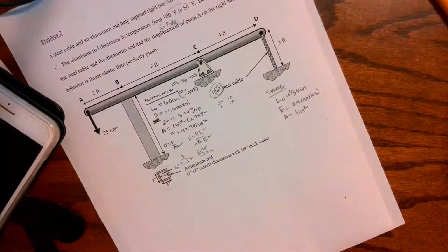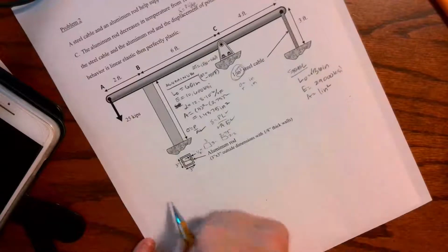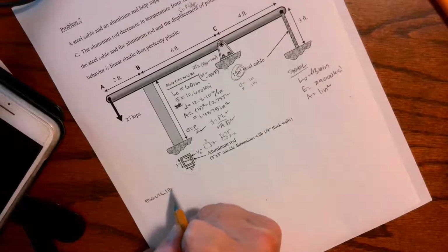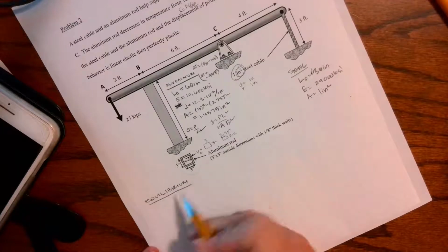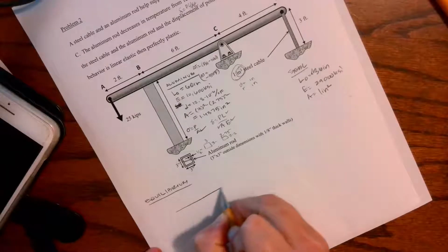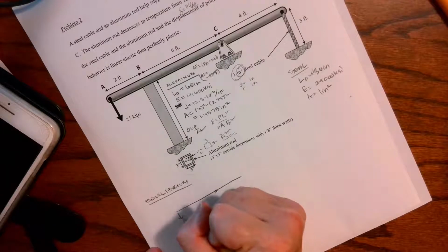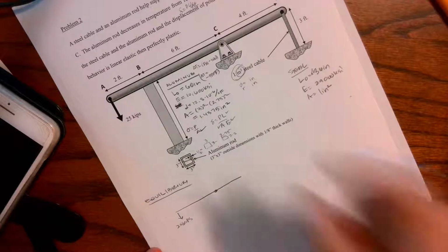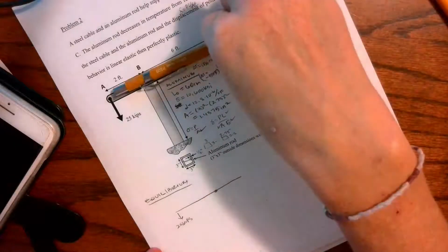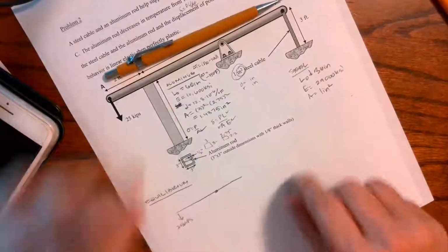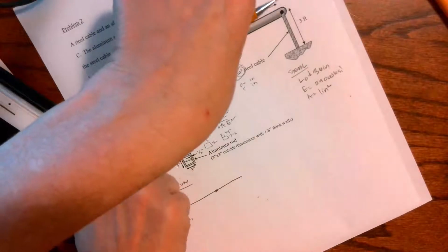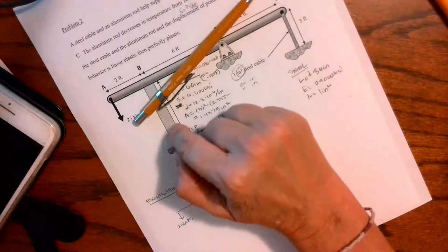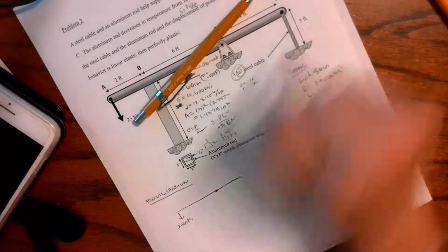Okay, so I have everything kind of in one place. So I'm always going to start with equilibrium. Equilibrium, that's my number one starting place every single time. And I'm going to just try to make some guesses as I'm looking at this. 25 kips pulling down, and I'm cooling down, so it's getting shorter. If this is a rigid bar affixed here at C, with a pin at C, then chances are, as I'm pulling down here, it's going to want to rotate something like that. And if it's rotating something like this, this is actually a compression member, and this is a tension member.